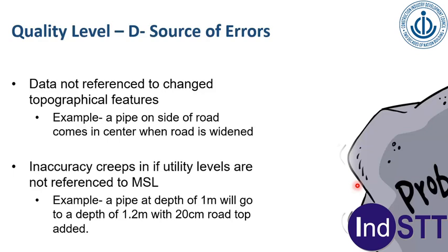The second most commonly used tool is the induction locator. GPR works on the principle of electromagnetic reflection. Here we are working on the principle of electromagnetic induction. So again, this is very good for detection of metallic utilities, electrical cables, etc. It cannot detect non-metallic utilities unless there is a tracer wire inside. Again, a different subject, but this is the second most commonly used tool.